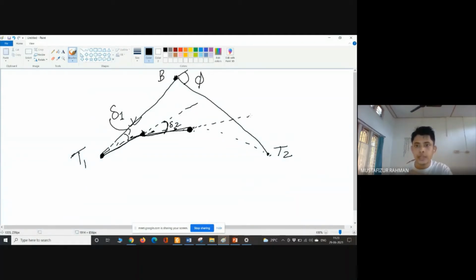Similarly, now we are looking here and we want to go another 20 meter. In which direction? In the direction of delta 3. So we will find out this delta 1, delta 2, delta 3 with our formulas, and we will find out the next point on the curve.